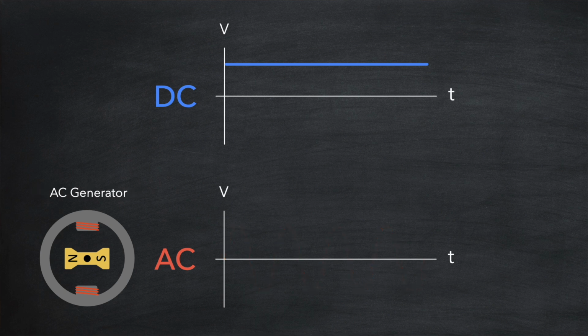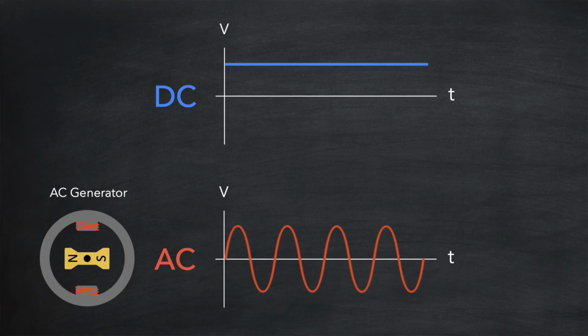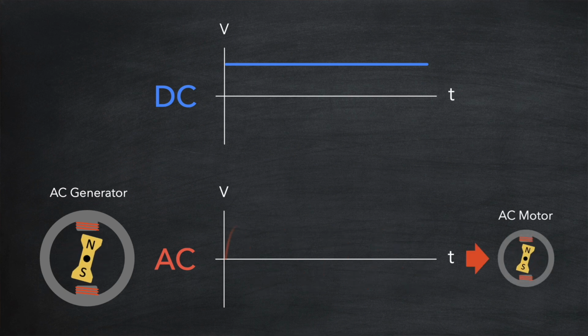We're going to burn coal and use the heat generated from that to spin a turbine which is attached to the generator. The moving magnets inside the generator will interact with each other and generate AC electricity, exactly like the AC waveform we saw. The speed at which the generator spins will determine the frequency of that wave, either 50 or 60 Hertz. Now, if we add a Tesla induction motor at the other end, we can use that waveform to spin that motor so it can be used to power factory machines, etc.